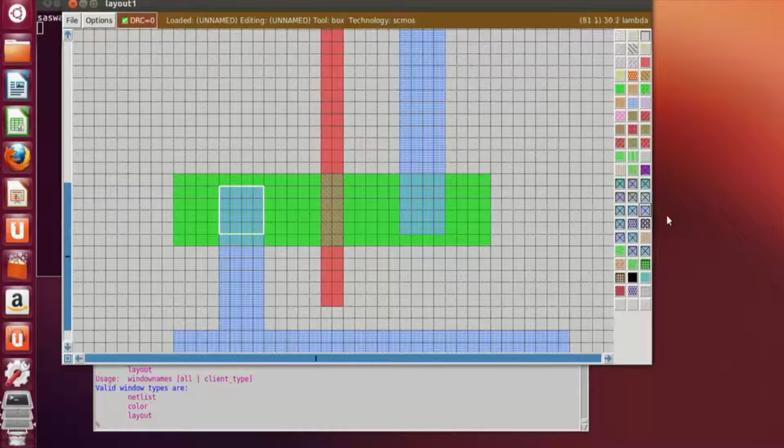Since this is the N diffusion layer and similarly this metal is connected, if you don't connect a contact, then this will just remain overlap, but this will not be connected. So just for your connection, we need these contacts. Middle click. In order to select, we use the middle click button, the middle click in the mouse. Now this is the ND contact.